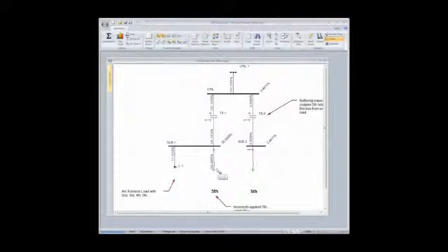You need to begin your notch filter application at the point where your first harmonics are appearing. I've actually applied 11th harmonic filters on a system with an active front end, and in that case, there were no harmonics produced even upwards to around the 17th harmonic, where it was actually some form of switching noise. So let's make sure that when we design notch filters, we properly specify. Now, the tuning point. Obviously, in this case, we can very quickly discern that we made a mistake by having this high distortion level.